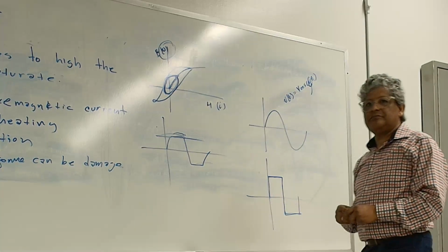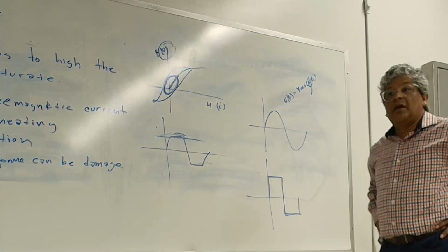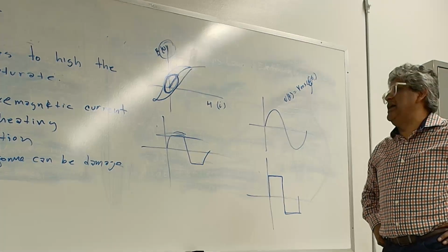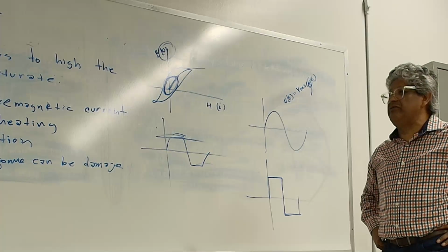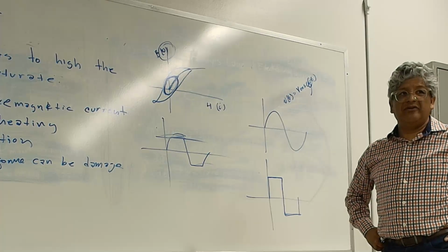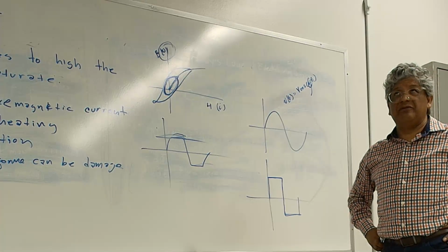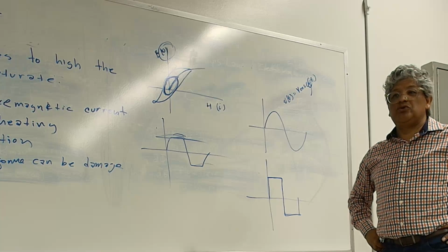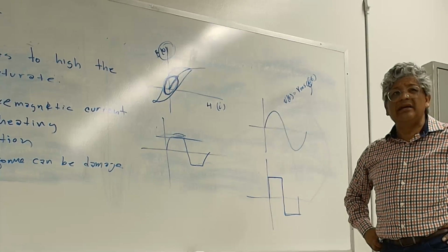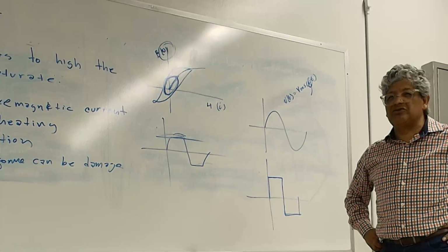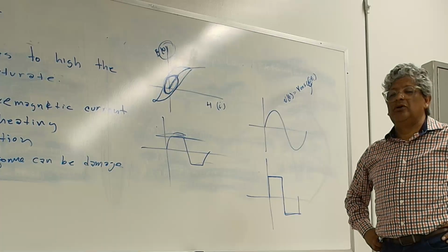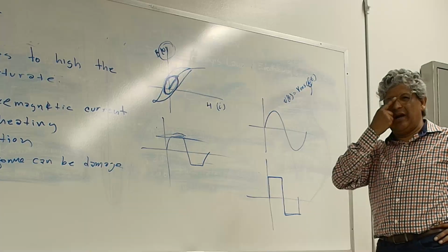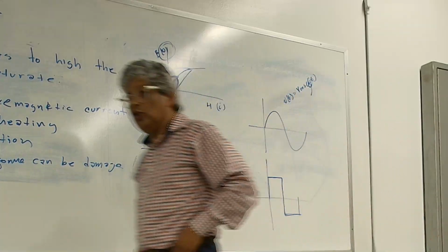Can you damage components on the receiving end if you start to see harmonics that are anything more than the fundamental? Yeah, you could. For the most part, loads are very resilient. But if there are certain loads that are very susceptible to harmonics or to any power quality issue, whether it's harmonics or sags or spikes, high frequency, you could damage the load.